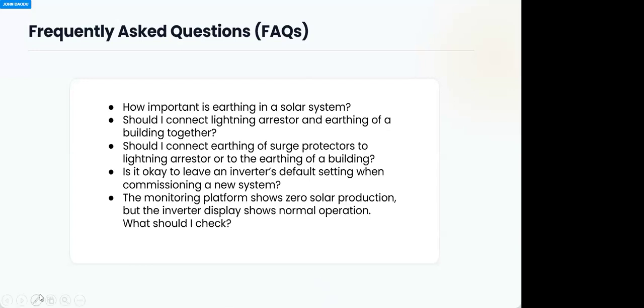Then before you go to the function, how do I want solar input to interact? Do I want solar to just go to the battery first, or should solar go to the load first, and all that? Do I want that anytime grid comes, it should be the one to power the load and cut off the solar, or when grid comes, grid should just power the load and allow solar to charge my battery? So all that are there. But the first set was those that I mentioned, the battery and the over-discharge point. So that's it.